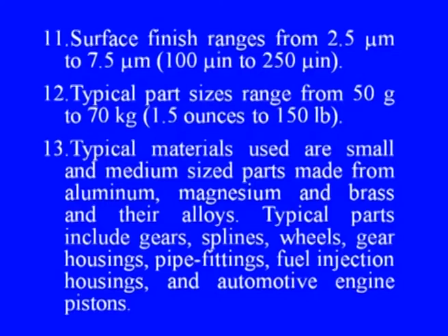The tolerances are 2% of linear dimensions. Surface finish ranges from 2.5 micrometer to 7.5 micrometers. The typical part sizes range from 50 gram to 70 kilogram.